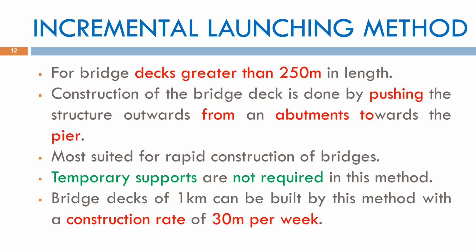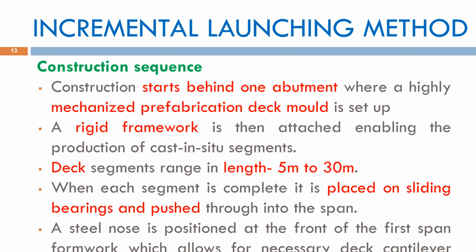One major advantage is that temporary supports are not required, reducing construction difficulties over rivers, valleys, or busy roads. Using this method, bridge decks up to 1 kilometer in length can be constructed at an average rate of 30 meters per week. The construction sequence of the incremental launching method begins behind one abutment, where a highly mechanized prefabrication